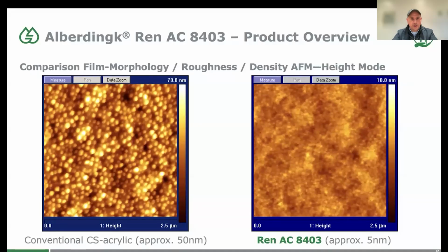And here you have to understand that the yellowish color, the very light color material, is hard polymer. And the dark matter underneath is the film forming matrix, the soft polymer. So what you're seeing here is spherical material with approximately 50 nanometer domain size. So in these 80, 90 nanometer particles, you have a hard material, which is probably like 50 nanometers in dimension.